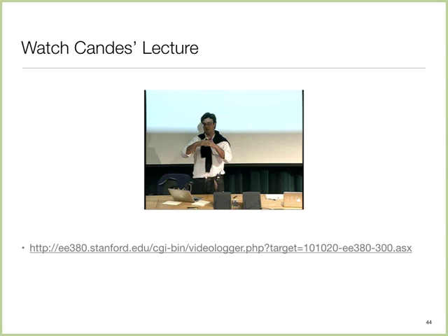There is a whole rich literature, and it turns out that compressive sampling and sketches were developed around the same time, and they are actually, deep down, equivalent. So this notion is tremendously useful. When it comes to minimizing the measurements, there are many different settings in which it becomes beneficial. First, every time you collect a sample, there is an energy cost incurred. You have to amplify the signal, and your A to D converter has to do a sample and hold and digitization. So you can save there.